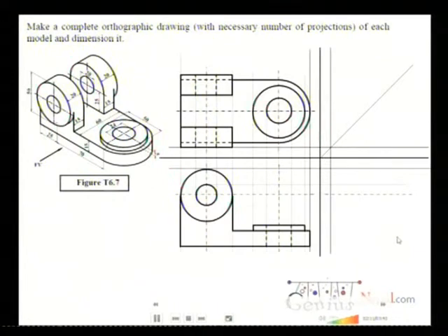Now to draw its side view, let me draw a mitre line and transfer the points from its top view to the mitre line to front view, and horizontal lines from all these points on this side. Center line. The intersection of these horizontal lines from top view and the mitre line would be here, and from these points we draw vertical lines as shown here, and at the intersection of this vertical line and the respective horizontal line we can find the position of the point.